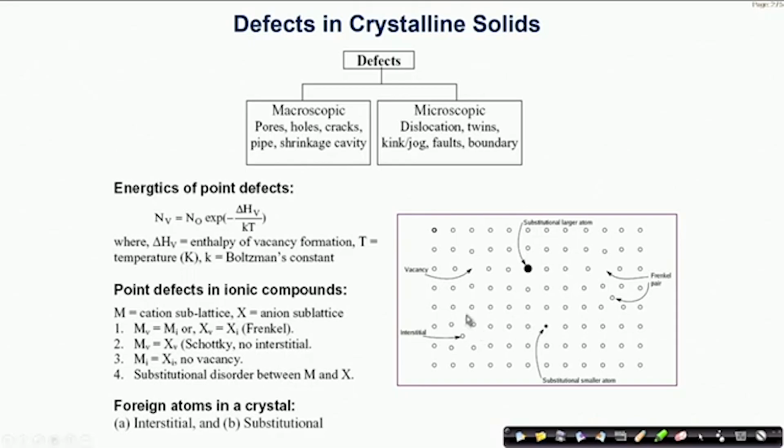And the portions which are left out, for example here, will have a certain dimension, and if you try to fit another sphere into these kinds of holes or vacant spaces, there is a limit up to which you can accommodate. The maximum diameter that one can calculate in these holes will determine the possible size of an interstitial atom that can fit in.